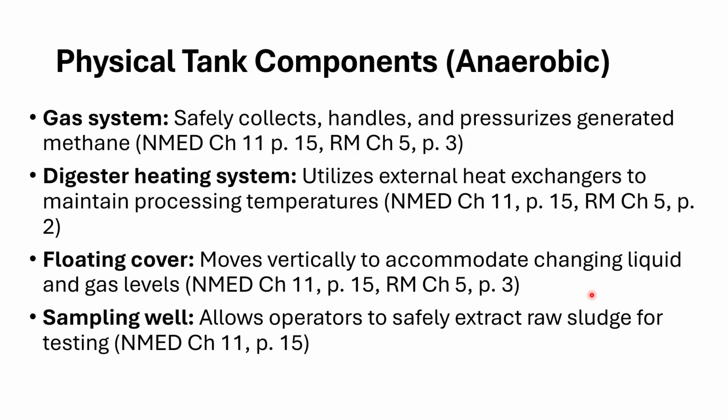Okay, we also have a sampling well, and please go back and take a look. You'll see the sampling well. That's going to let operators take out raw sludge for testing. What we're looking at for testing is like the mixed liquor suspended solids. We're looking to see what kind of microbes we're pulling, what kind of BOD we have. Pretty interesting stuff. And we will go over that a bit later when we hit the activated sludge chapter, okay?